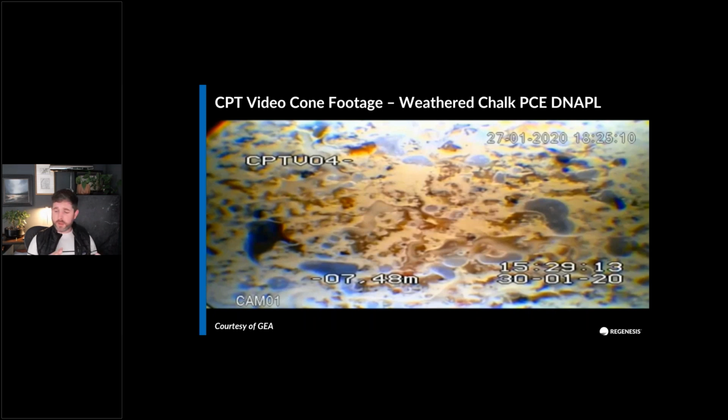So if you can't find the DNAPL on your site, I would say it's very common. I've worked on perhaps hundreds of chlorinated solvent sites as an example, and I can only think of 5 where they actually found evidence of the DNAPLs. Of course, this is different if you're looking at creosotes and coal tars. Often you can find those, but understanding if the contaminant sinks or floats is important because it's going to influence what we inject where.